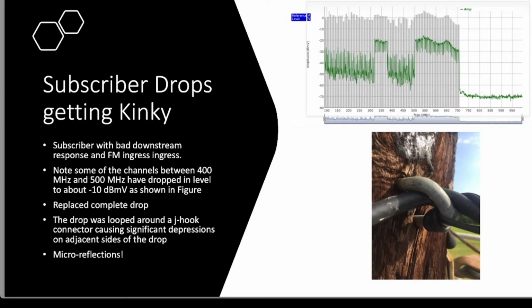And we know that when there's FM ingress coming in, oftentimes that means there's return path noise that comes into return. This particular house was allowing a huge amount of return path ingress. And that was really the reason that we visited this house: a massive amount of return path ingress that was coming back all the way to the CMTS, which then, as we know about the funneling effect, impacts all of the subscribers. But when we got there, we saw it had other issues as well.